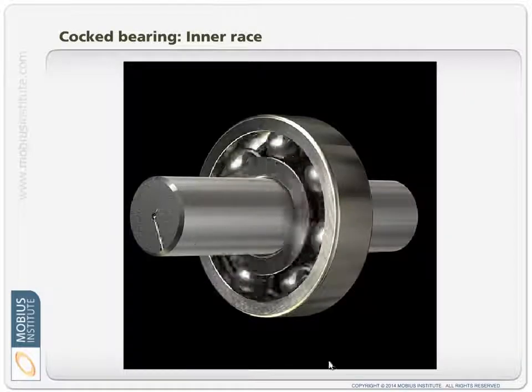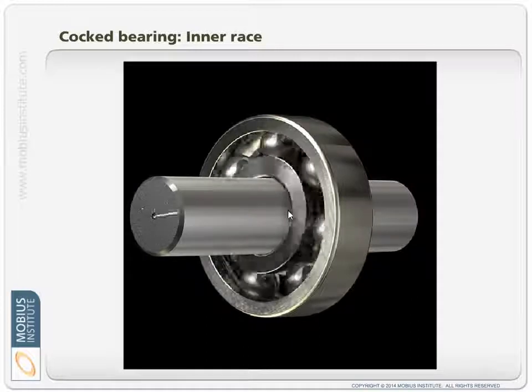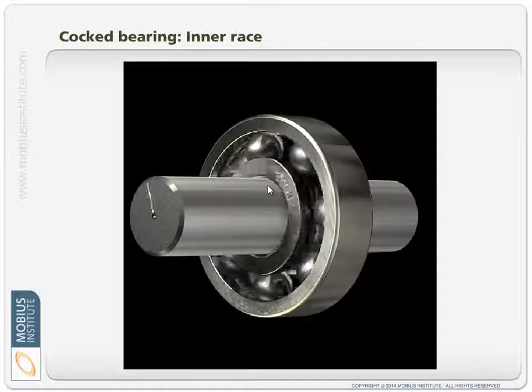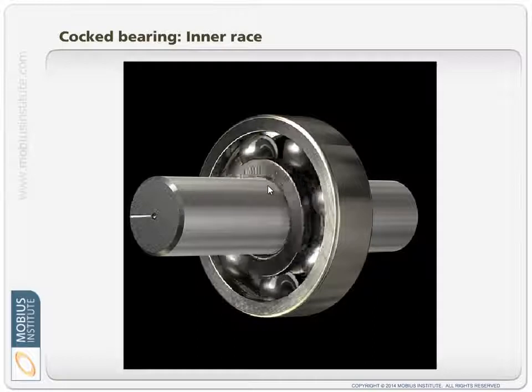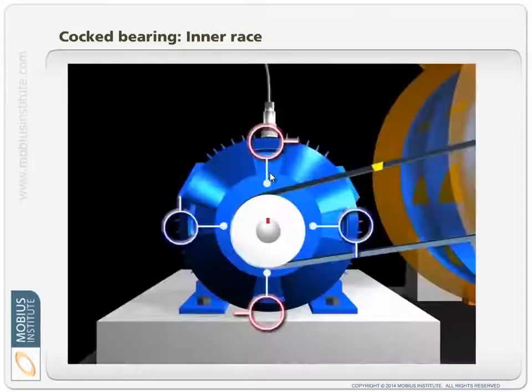And oh look, the bearing isn't mounted correctly on the shaft. It's rocking and rolling every time the shaft turns, which is damaging our bearings. But if we compare the phase from here to here to here to here, we see a 90 degrees phase shift because of that rocking motion. Now, yes, we wouldn't take a reading here because we've got belt. I need to come up with a better illustration, but anyway, that's what we've got.